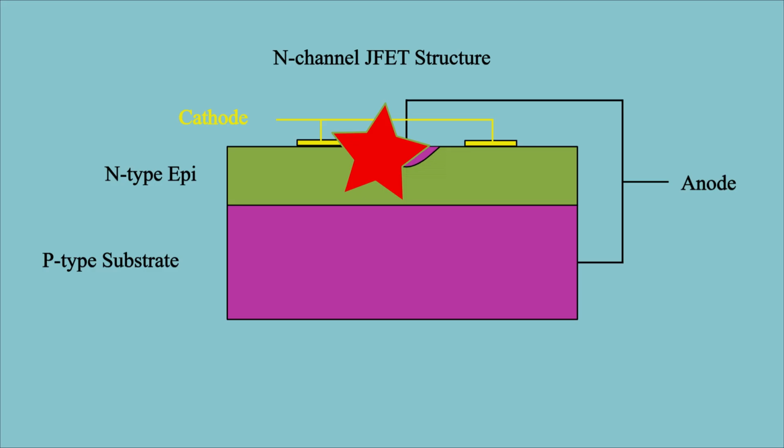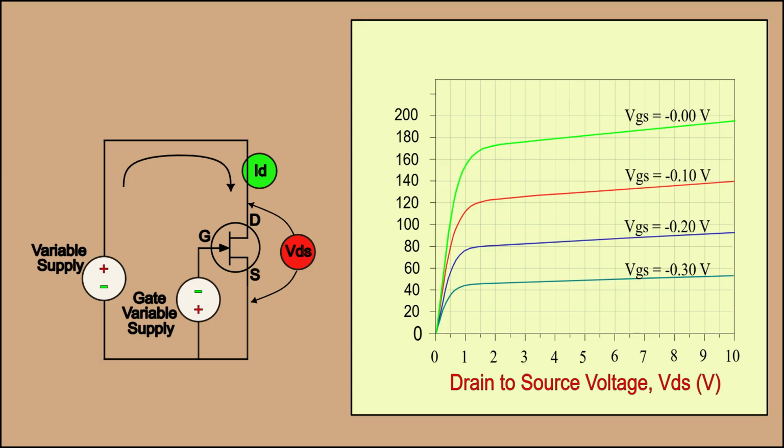Another thing to consider is distortion. Remember that the lines in the ohmic region change from mostly vertical to mostly horizontal. If the input signal peak excursions are too much, they raise the drain voltage too high, where the resistance is not a straight line and the result is distortion. This is possible on both the positive signal highs and on the negative signal lows.